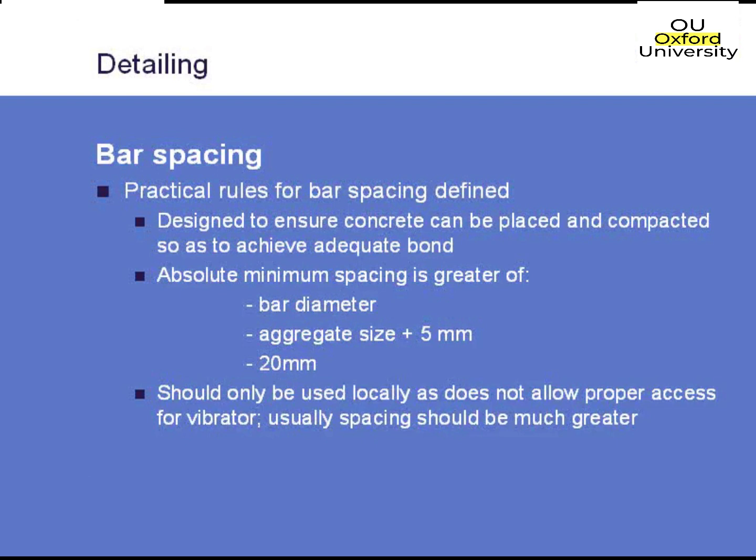Those practical rules you still have to observe. Those minimum spacing requirements are something you only put in very localized regions. Don't put them everywhere, because you're going to end up with other durability problems, just because you're not going to be able to vibrate the concrete properly.